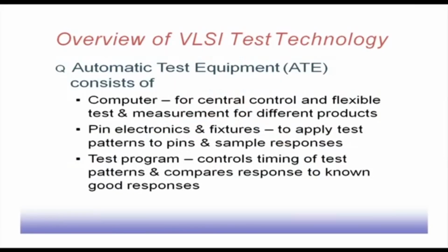It depends on two factors: the channel width, and also the memory capacity that it has. There are challenges, as IC technology is increasing significantly. Chips are becoming more and more complex, but most companies, the fabrication house or the testing company, will have one ATE of a certain capacity. It is not advisable that with every new chip that we design, we have to have an ATE that can run at a higher speed. With every new version of chip running at higher speed, the ATE speed should also go up. So, there must be some technique by which we can use these older ATEs for the faster chips as well. That is also a part of this ATE design.